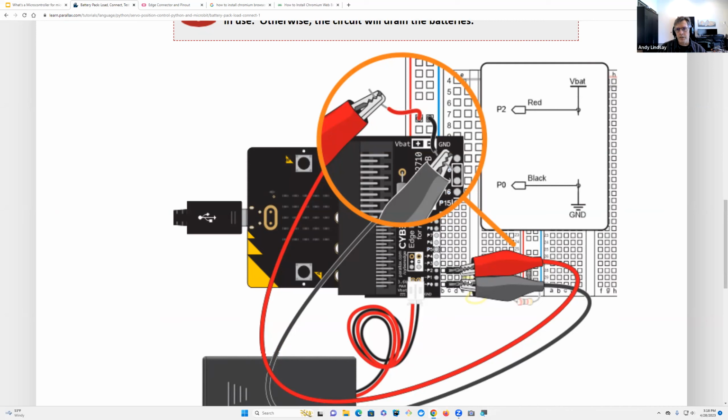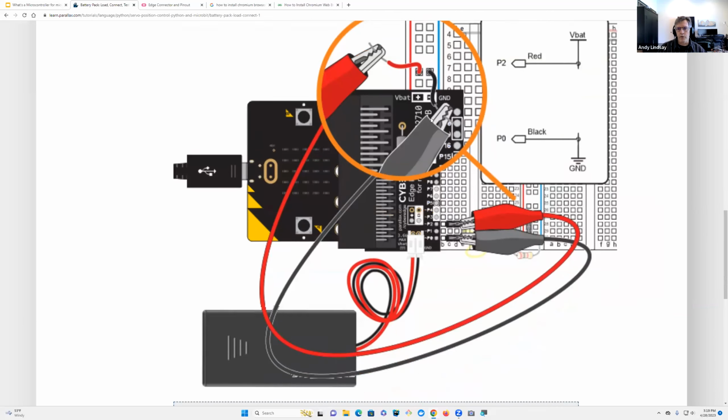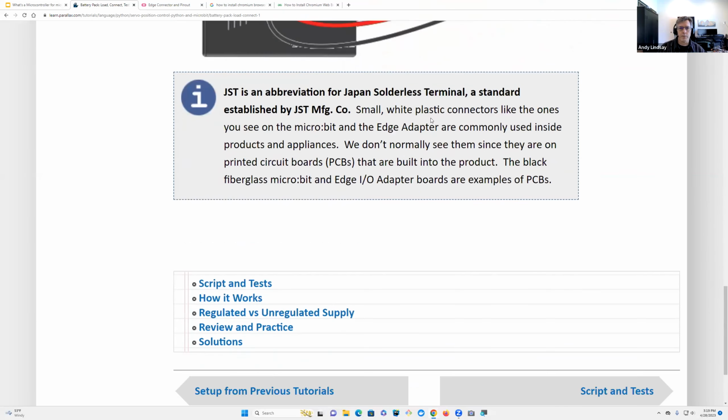Also I think that this is a situation where we want to make sure that the 2 probes are not touching each other. So make sure that the metal of the 2 probes that you have are not touching each other. And after that, go ahead and plug the alligator probes into the left and right sockets. And what we're going to do is put batteries in the battery holder and measure the voltage.